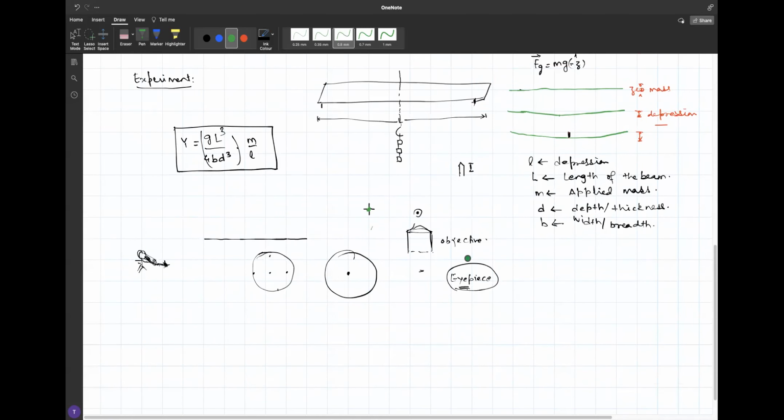Okay, so now you saw the experiment, you saw the video, you saw where you apply the masses, and this was rested on a pin here, right? And a pin here, basically, so that there are no other contact points. It's a very small contact point, and whatever mass you're applying, you're applying on the beam, and you assume that it's uniformly distributed, because the beam also consists of many small units, right? You assume it is isotropic and uniform, a homogeneous material, and whatever you apply here basically tells you what is going on in the whole beam, right?